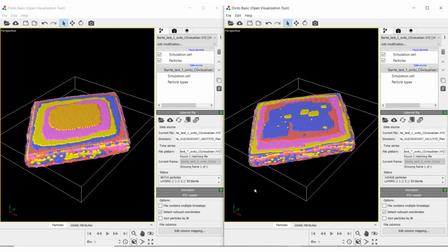So that's a few examples of checkpointing, how you can use it to grow a seed crystal or to recolour a crystal. If your simulation fails because it reaches the box edge, provided you've enabled checkpoint saving, it will save a checkpoint at this time, so you can then load that simulation into a larger box if you want to carry on growing it. So that means you don't waste any simulation time.